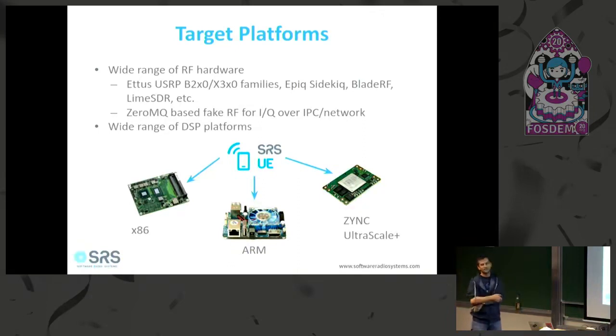Just because of all the SIMD that is required, and even ARM. It does have SIMD, but even if you have a powerful Snapdragon or Raspberry Pi 4, it's still hard. I mean, you can run smaller bandwidths, like 6 PRBs is probably okay, but a 20 megahertz LTE signal, there's no way you can run the entire PHY in ARM. But it's getting better.